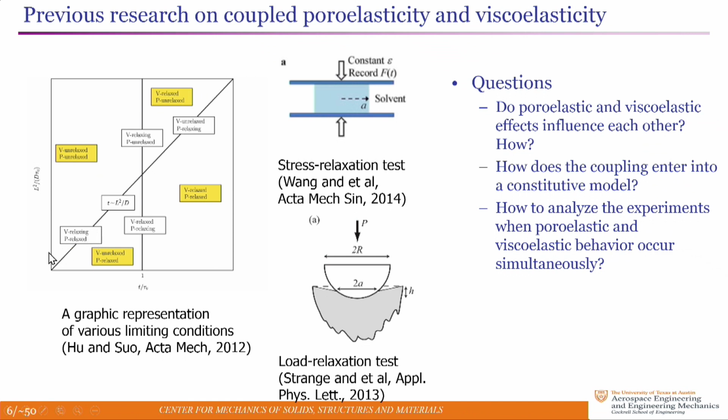So if you're in short length scales, diffusion can complete itself and your poroelasticity is fully resolved. But if you go to very long specimens, poroelastic diffusion hasn't completed, and you'll have an effect based on that. If you're at intermediate length scales and time scales, you have a coupling between what happens in porous flow and what happens in viscous deformation.